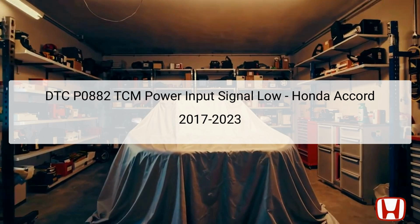When this error code is identified, it suggests that the TCM is not receiving the requisite power to function effectively, which can lead to degraded transmission performance or failure. Diagnosing this issue correctly requires a systematic approach that includes verifying the DTC presence and assessing the electrical systems involved. The following slides outline a detailed troubleshooting guide aimed at diagnosing and rectifying the issue associated with this code.